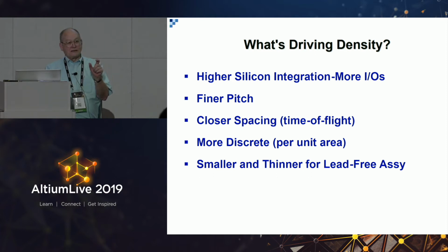So it draws nearly 200 amps at a low voltage. So it's an enormous cooling problem, but it's also an enormous signal integrity problem with that many devices. And that's a relatively old device. Like I said, TI showed me some 5,500 pin devices coming down in a year or two. So it's just going to keep going.